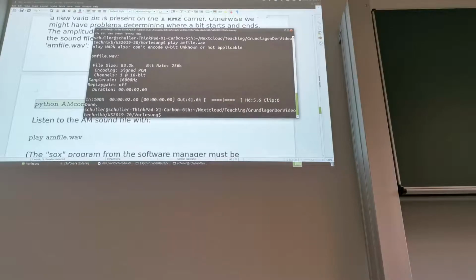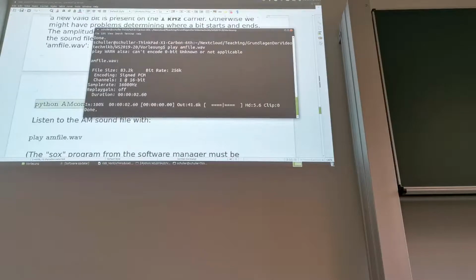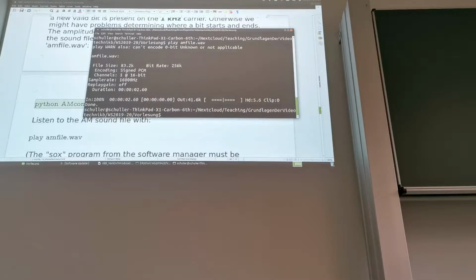So there's a low tone and a high tone. The high tone is beep, beep, beep, beep, beep, beep, right? And then there's this lower tone which sometimes goes off. So da, da, da, da, da. Right? So the low tone contains the bit information. This high pitch beep, beep, beep is the bit rate, the clock for synchronization. Yeah, so this shows you that it's actually advantageous to listen to the sound, because using the ear, you can really distinguish those two tones.